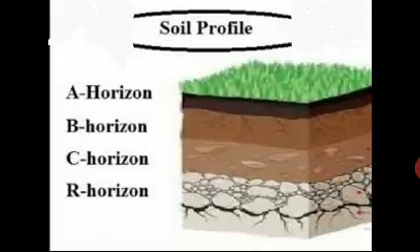The fifth factor is permeability. It is an important quality of the soil that enables it to transmit water or air. It is defined as the velocity of flow under a unit hydraulic gradient. It depends on presence of minute openings in the soil, size of the openings, shape of the openings, arrangement of openings, water temperature, soil texture, and soil structure.